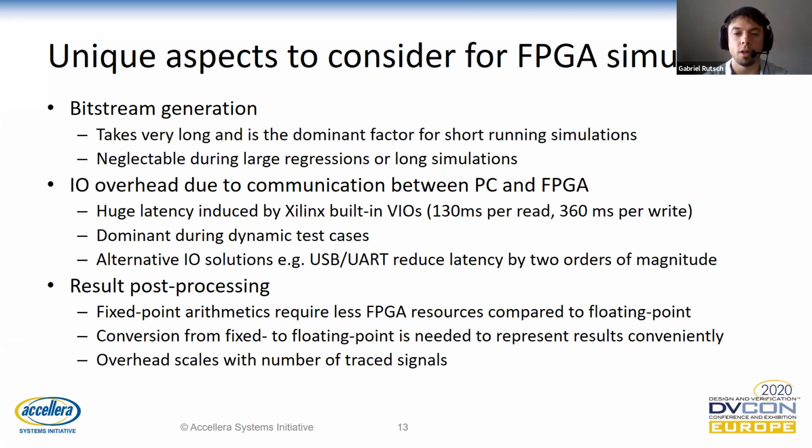The simplest solution to communicate from the host PC to the FPGA, in the case of a Xilinx FPGA, is to just use the built-in virtual IOs. However, they introduce quite a lot of latency to the overall system. So a read takes about 130 milliseconds and a write even more, 360 milliseconds. And especially if you have a dynamic test case where you quite often need to communicate between the host PC that is scheduling or running the test case and the FPGA, this adds a lot of simulation time on top.